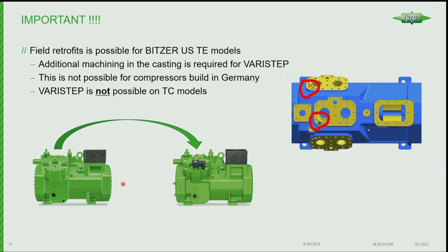Like I said, we do have a lot of stores in Europe, especially, that have both. They have a VFD and an unloader, just to really fine-tune that suction pressure and keep it nice and stable. The issue that I had with the VFD would be that it would ramp too low and I'd lose my oil pressure. Yeah, so that is individual to the compressor. You're going to have lower mass flow going through the compressor, but the oil is going to come back based on the mass flow of the system.